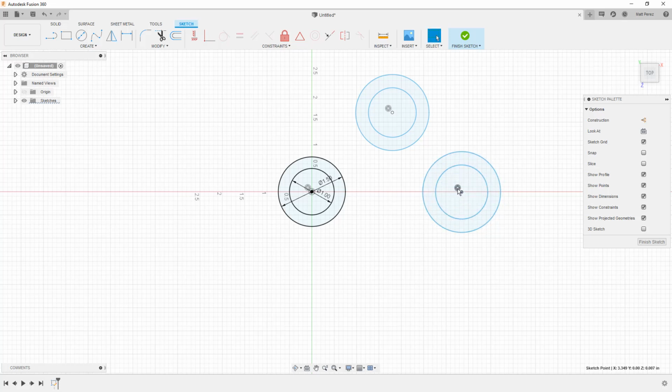When we look at this, there is a constraint that is applied, and this is a concentric constraint. This is done based on how we're sketching. Now, as you begin to sketch, if you don't like those applied, you can hold down the Control key, which will override those persistent constraints. But don't worry too much about that for now.